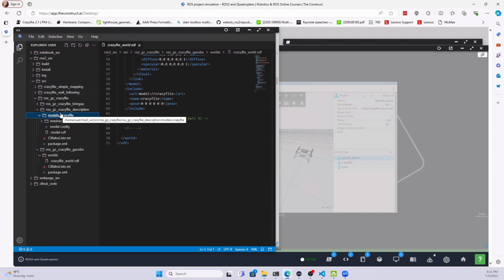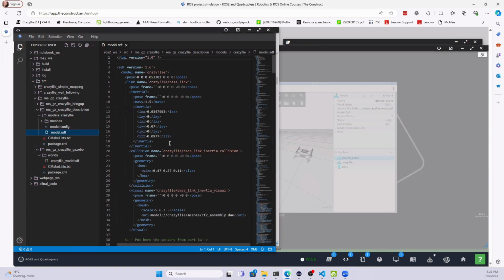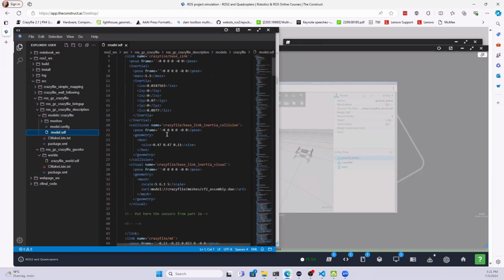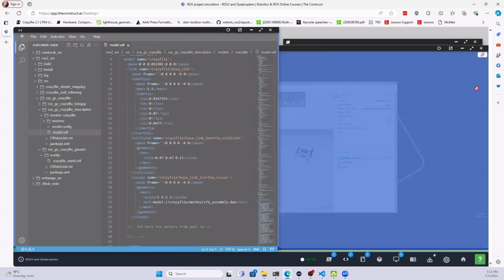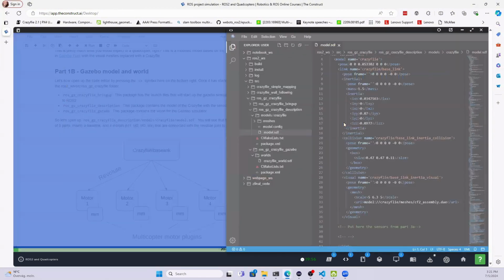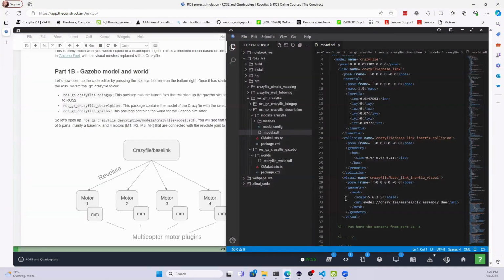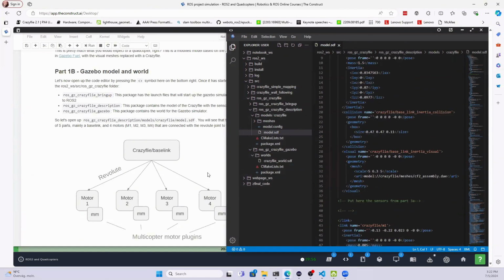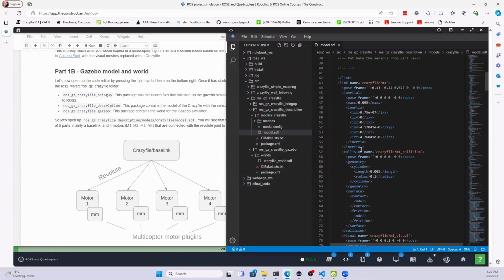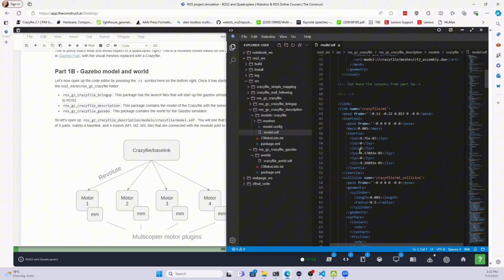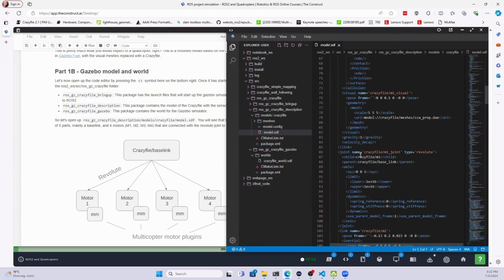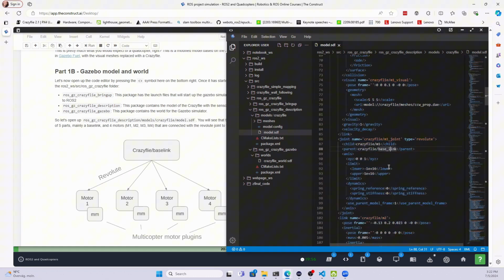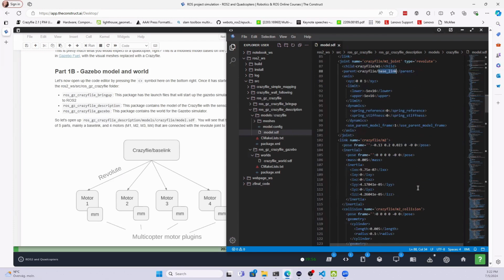This is the part that I had to source in my terminal before in order for Gazebo to find it. And practically, it's not as complex as an arm robot. It only has 5 features, which is a base link that is connected to 4 motors with a revolute joint, so that you can see right here. M1 is motor 1, motor 2, all connected to the base link.